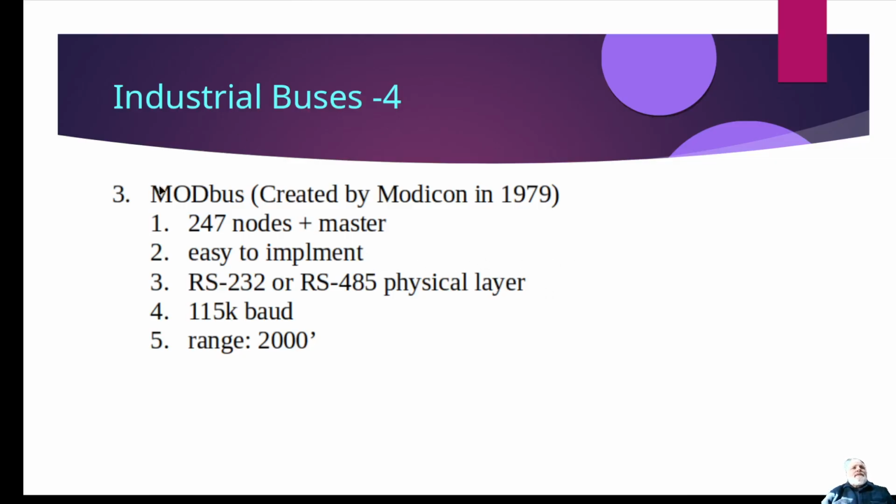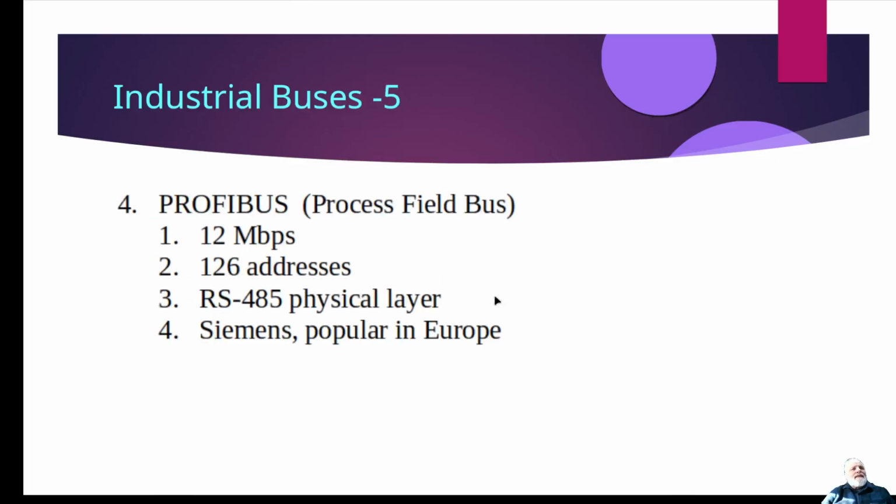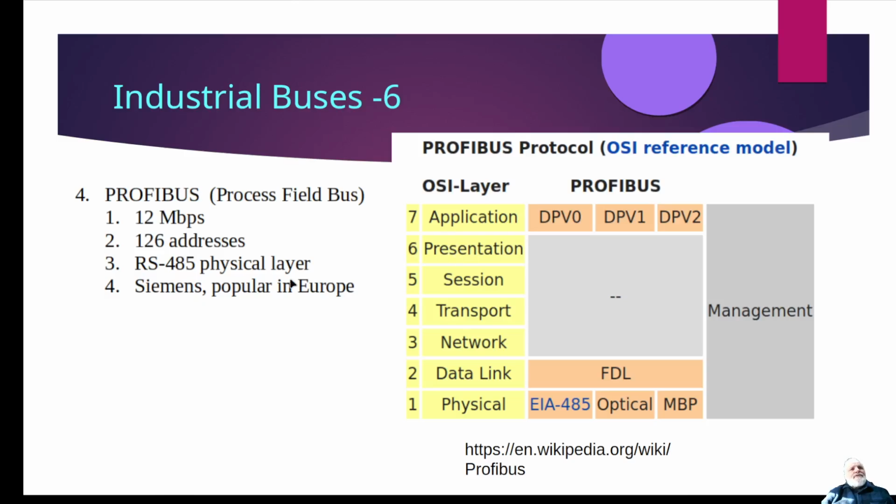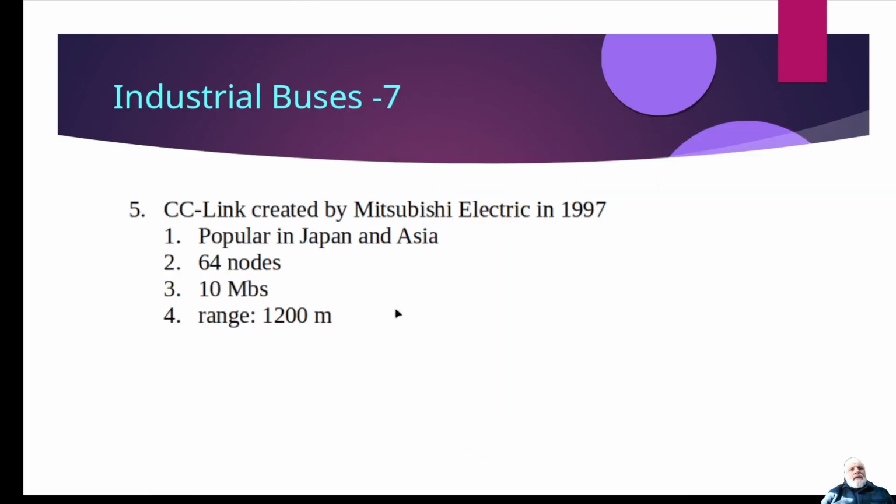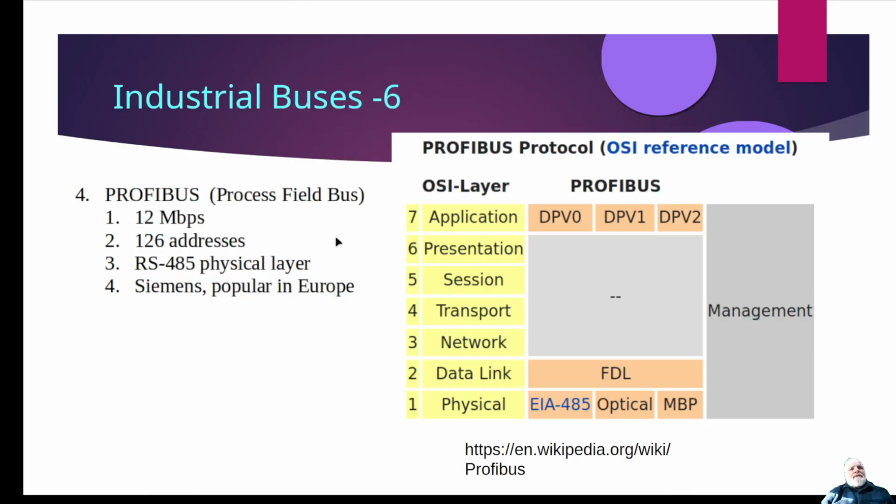And then there's Modbus. Modbus was created by a PLC manufacturer called Modicon, and it's very similar to the other two. It's not used that much, but Modbus TCP is, so we'll get on to that. And then there's also Profibus, which has evolved into Profinet.